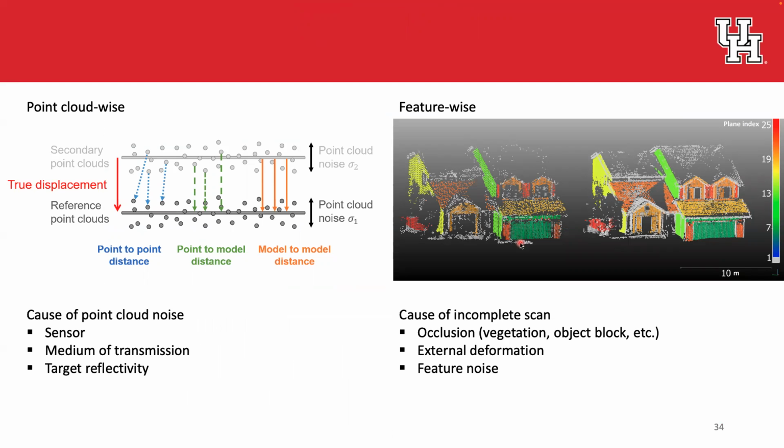So yeah, I kind of glossed over that, but we qualify the planes a little bit on the front end. If they are not nice and flat surfaces, we don't consider them for the least squares adjustment. In this house, most of the points are used, but you can see there are a lot of points not included in the model, because we looked at them and said they're not planar enough for what we want.